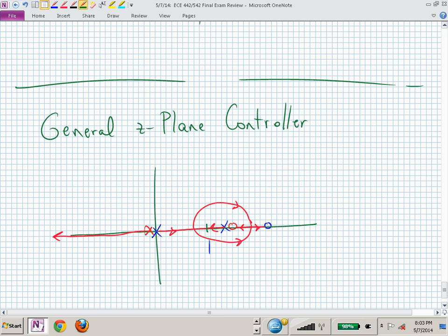So the gain to get to 1, which is right here, we need to get this rightmost pole inside the unit circle, don't we? And we hope that in the process of cranking up the gain k to get to that, this leftmost pole doesn't zip outside -1. So what we're hoping is that we get something like that.